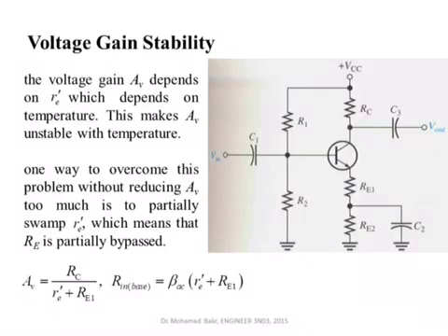One other reason for doing that is what's called the stability of the voltage gain. Most transistor parameters are functions of temperature. RE dash is very small. It's few ohms, and it does vary significantly with temperature. So if you have only RE dash in the denominator, as shown here, if there is no RE1, this may cause significant change in your gain if the transistor starts to heat or starts to cool down. And this is something not desired. So if this is few ohms, maybe add something which is way more stable with temperature, does not depend on temperature, to increase the stability. It will reduce the gain, but it will also increase the stability.